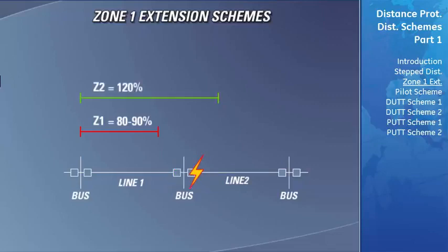If the permanent fault were picked up by the D60's Zone 2 because it was located at the beginning of the next adjoining transmission line, the relay protecting that transmission line would pick it up in its Zone 1 area of protection and clear the fault. The D60 will then continue to use the shortened Zone 1 area of protection until the auto recloser sequence has expired. At that point, it will revert to the extended Zone 1 area of protection.